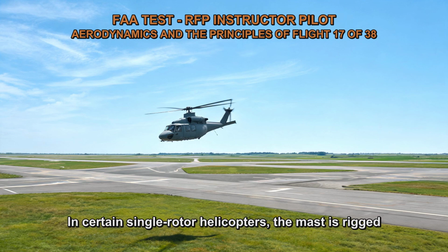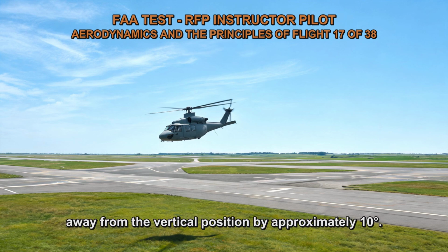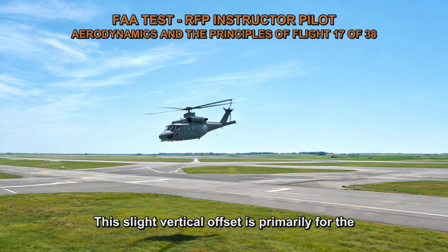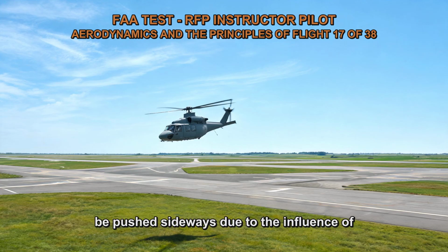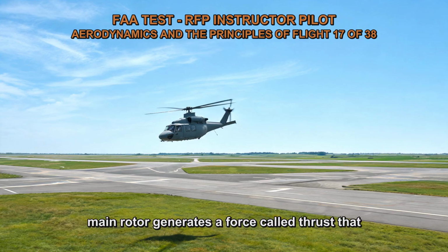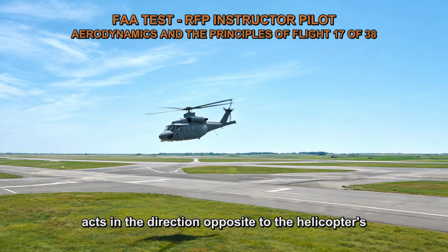In certain single-rotor helicopters, the mast is rigged away from the vertical position by approximately 10 degrees. This slight vertical offset is primarily for the purpose of counteracting drift. Drift is the tendency of the helicopter to be pushed sideways due to the influence of crosswinds or other lateral forces. When the helicopter is in forward flight, the main rotor generates a force called thrust that acts in the direction opposite to the helicopter's motion.